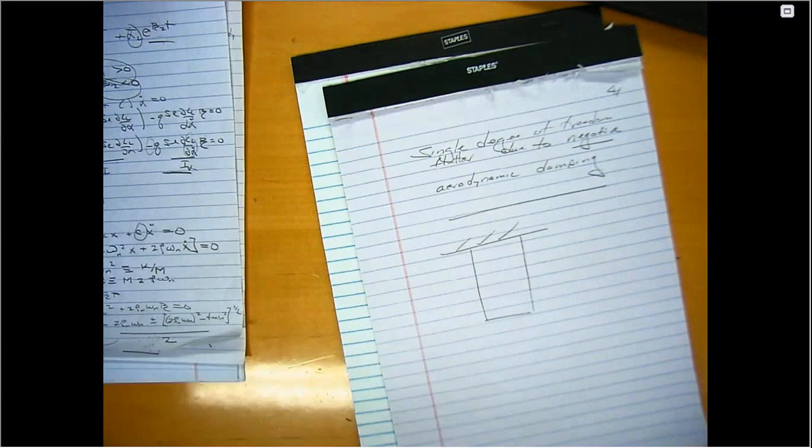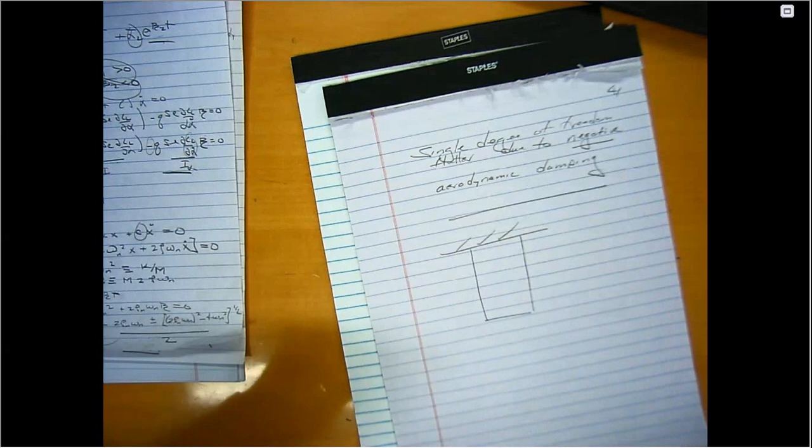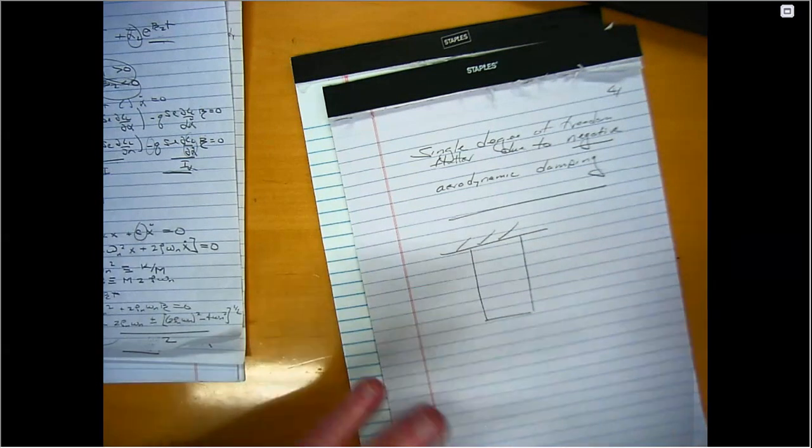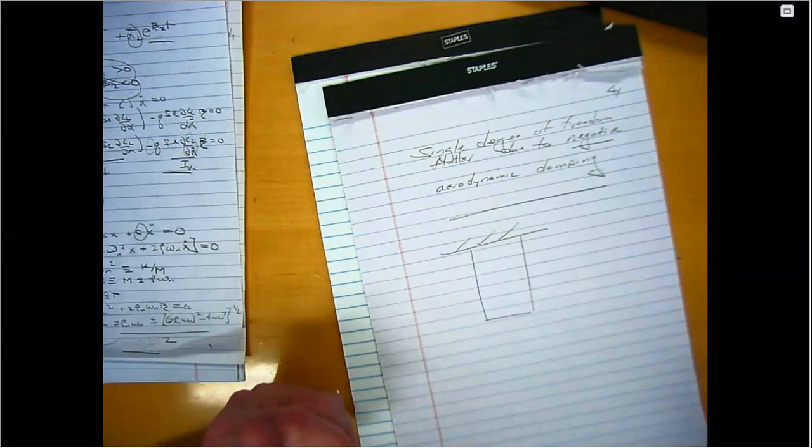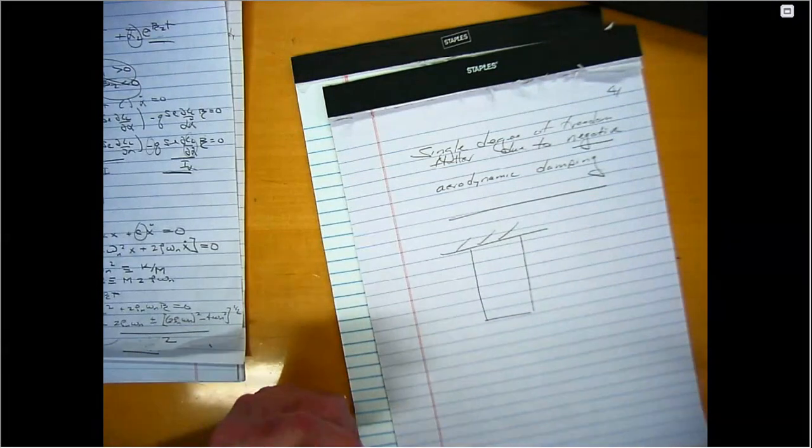And in an airplane, there are the modes associated with the horizontal tail, the modes associated with the vertical tail, the modes associated with the wing, and then the overall modes, because all these things are connected together through the fuselage. So there are a lot of modes potentially. In an up-front analysis of a real airplane, people might use dozens of modes in the models, and they have to track all of them.